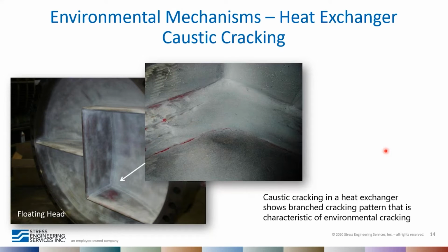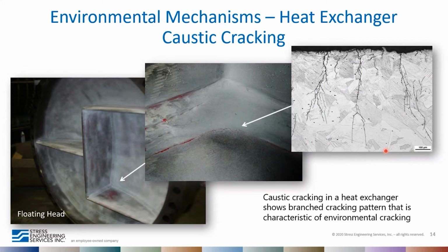And at various points in the component, you can see signs of cracking as a result of the exposure to caustic. So we did a series of assessments to evaluate these cracks. The micrograph shows a branched cracking pattern that's characteristic of some of these environmental mechanisms.